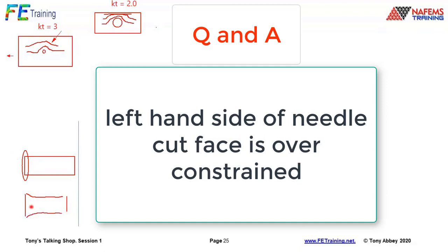My argument there, John, is that I'm far enough away with my St. Venant's principle playing a role, that the diffusion length, the local effect, is let's say 1 diameter. I've come further than 1 diameter away. I'm looking at stresses upstream here, over here and to the right of that. So my argument is that yes, that is a local effect, but by the time I get here, that effect has diffused, so there isn't an issue with that. That's the argument I would be applying there.